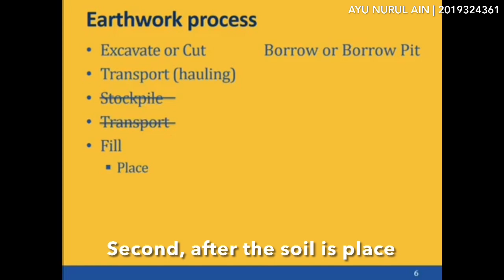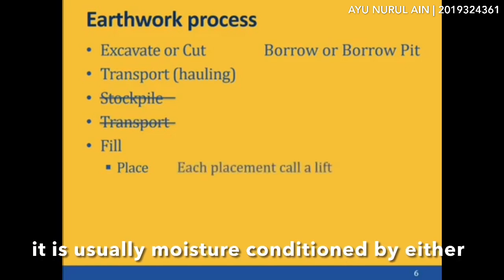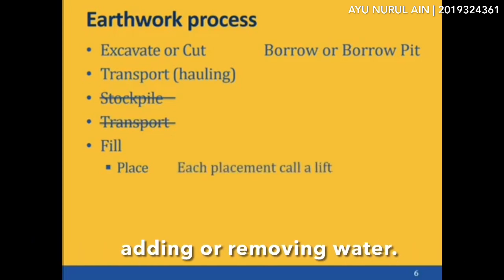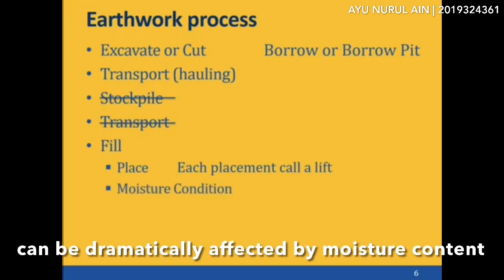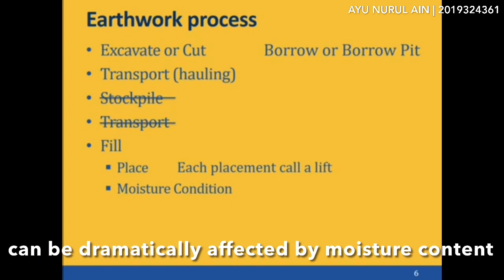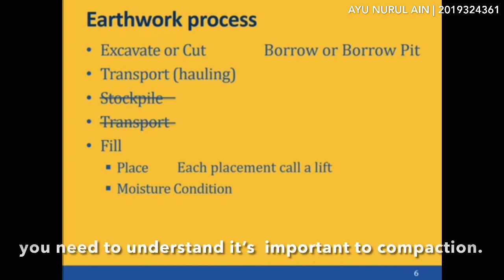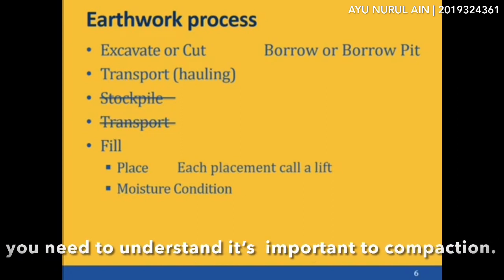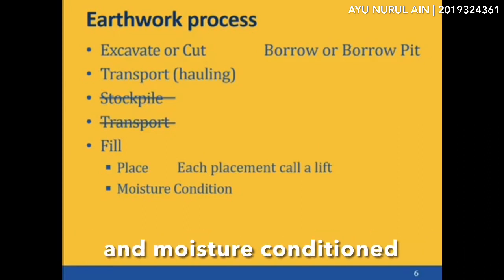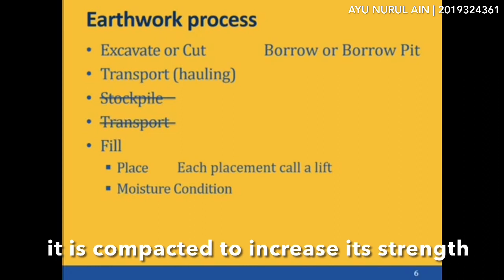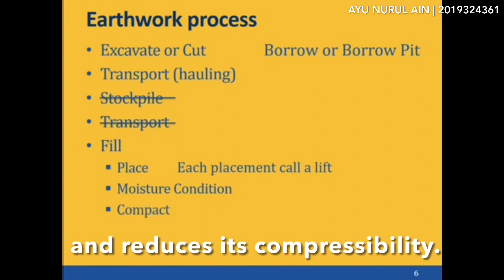Second, after the soil is placed, it is usually moisture conditioned by either adding or removing water. By now, you should understand how soil behavior can be dramatically affected by moisture content. You need to understand it is important to compaction. Third, after the fill material is placed and moisture conditioned, it is compacted to increase its strength and reduce its compressibility.